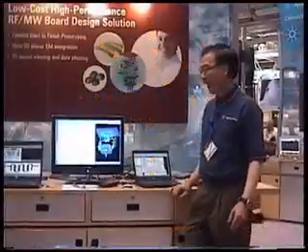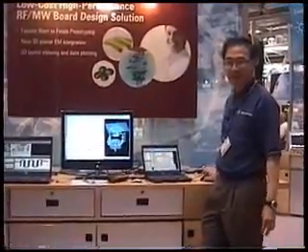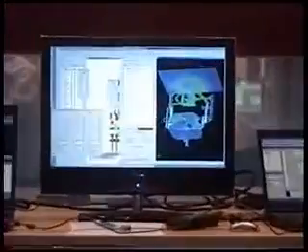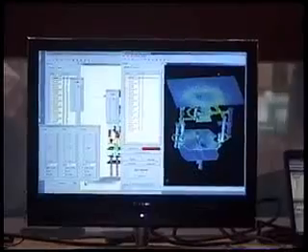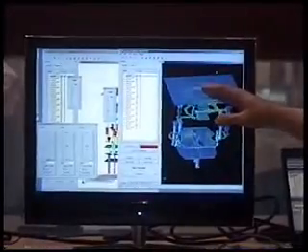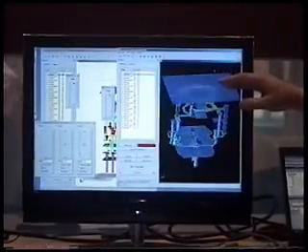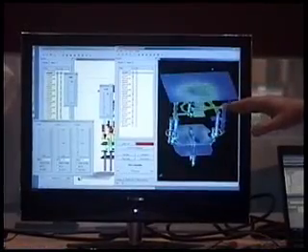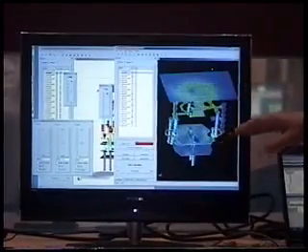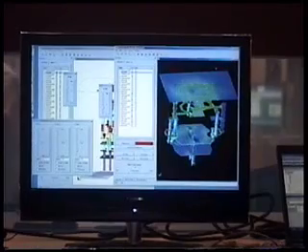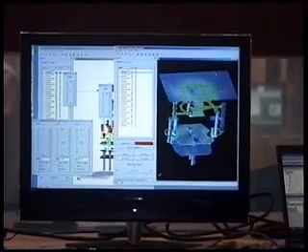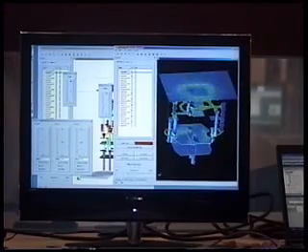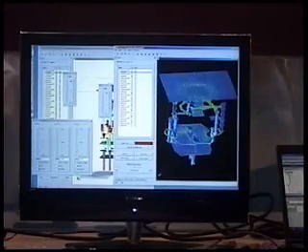So what I'm showing you here is the latest EM simulator, Momentum GXF. It's a planar electromagnetic simulator, and what you're seeing here is the solution of simulating an LTCC filter. It's a multi-layer, three-dimensional filter, and what we're seeing here is the final solution, and we're looking at the surface current flow across the planar structure as well as through the vias in the vertical structure.